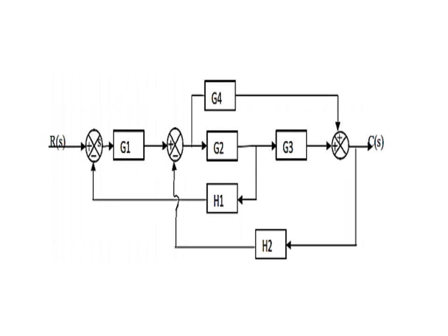After that, the third summing point will be removed. Then again you can have a simplified diagram, and you can simplify the whole system and find the overall transfer function. Here the main point is, first you have to identify which point should be shifted. That is very, very important. Here I chose the point between G2 and G3.